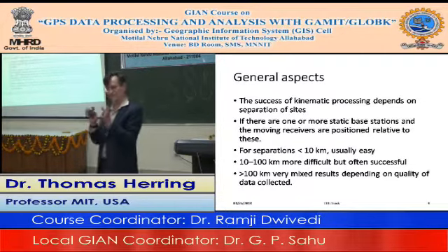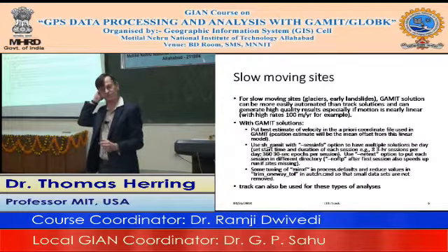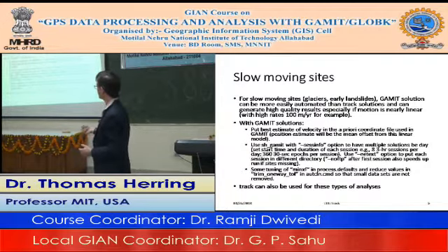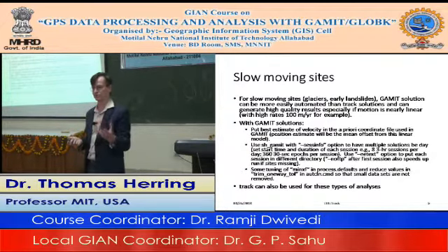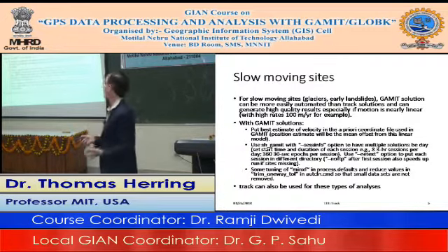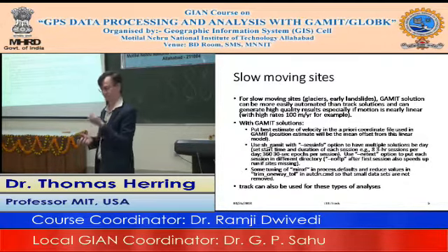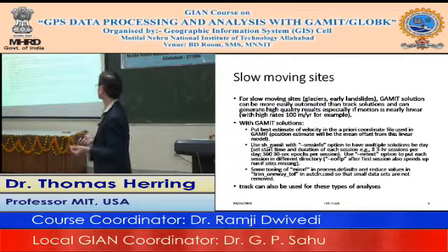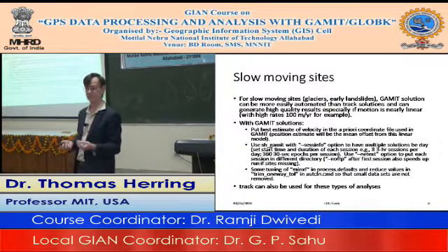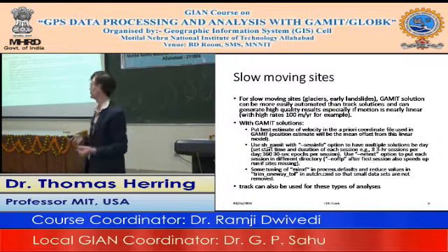So there's a subtle point for any of you who want to do this: what is the nature of your kinematic site? And for slow-moving sites, many people use track for lots of different things. We have lots of users who put receivers on glaciers, and some people put them on landslides. On glaciers, depending on which part you're on, they can move very rapidly, in fact several 100 meters per day in some cases. In other cases, they're moving 10 meters per day, etc. And kinematic processing is certainly one of the ways you can handle that.